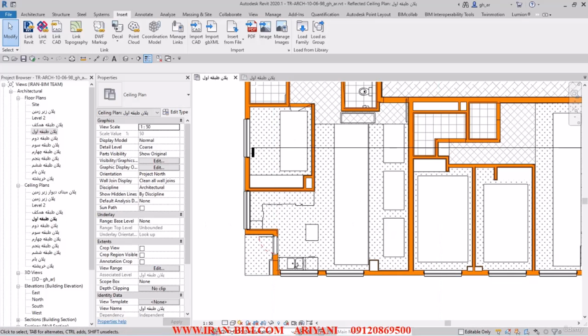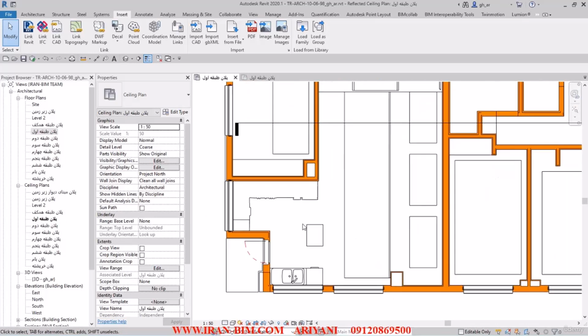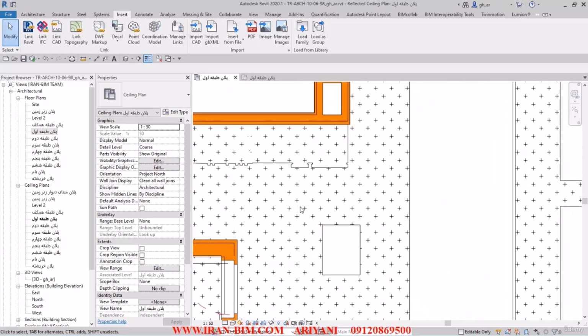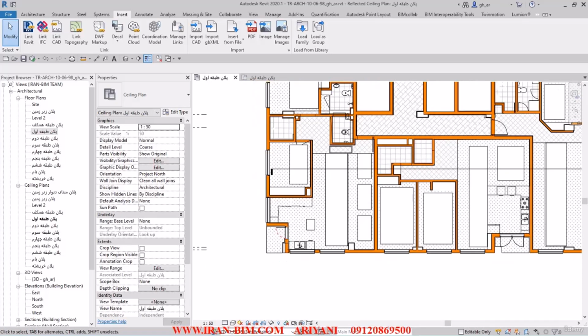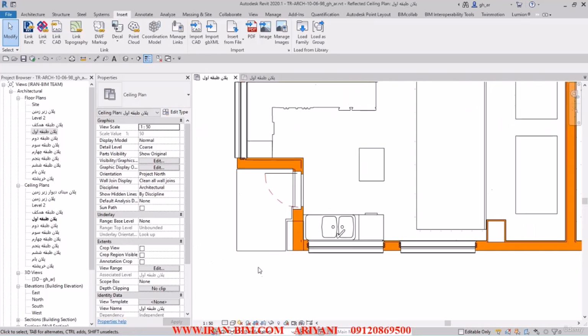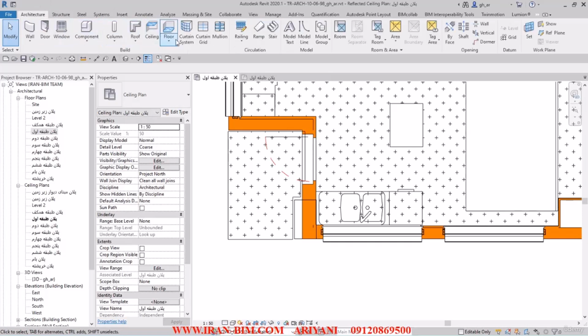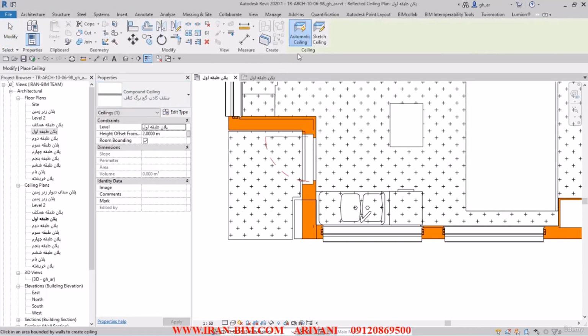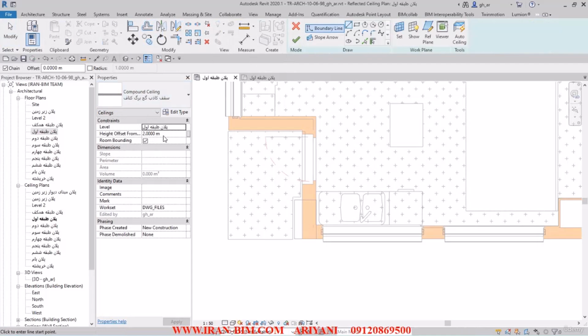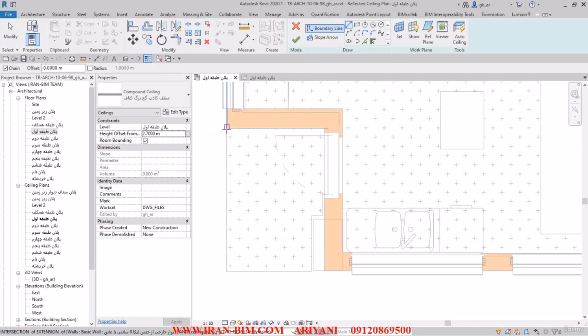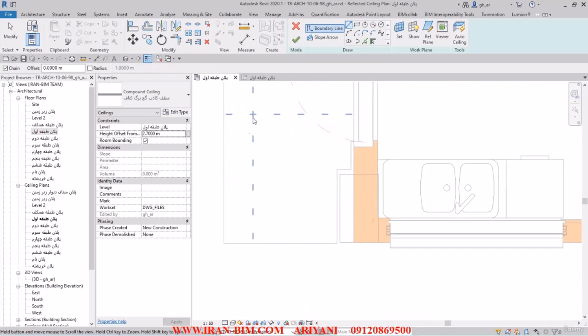And the hatching that you see over here that's done with these small pluses, it's talking about the 2.7 height. Let me just open up the CAD file here as well so I don't make any mistakes. So I'll go here and then I'll pull this up. And then from the menu, I'll select the ceiling tool, then sketch ceiling, and then I'll put the offset on 2.7. Then we start the drawing.